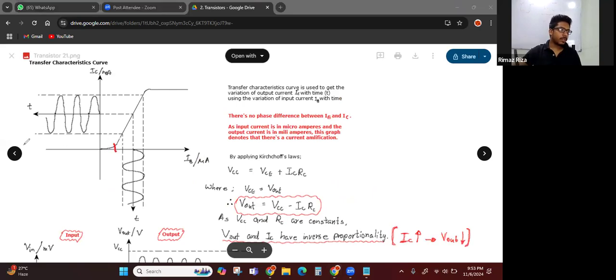So here this is cutoff region, right? To here cutoff region. This is cutoff region, and from here to here it will be active region and the saturated. So amplification process should occur within the active region. Suppose let's say this value, suppose this comes to here, then it will be a disaster. We can't amplify as we wanted. Do you all understand?